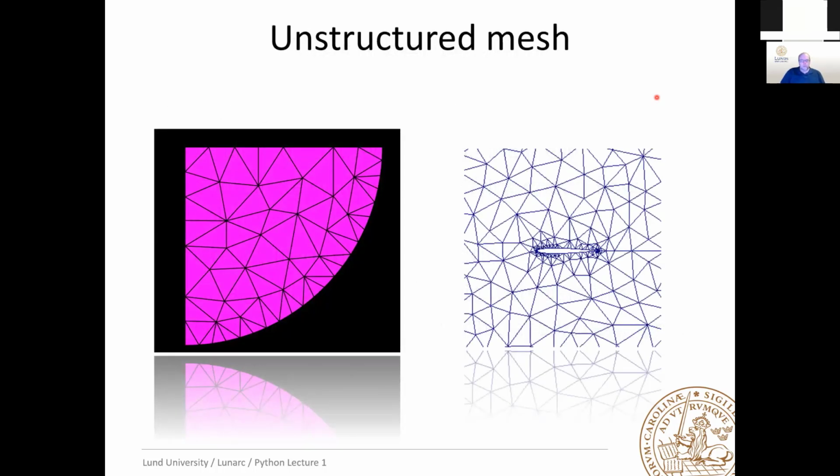This is an example of an unstructured mesh. Here you can see that you have a geometry, and then you have basically poured the elements inside the geometric boundary. The algorithm will fill the mesh with points and then connect them together to form a mesh. And usually these mesh algorithms start from the boundaries and move in. You can see the kind of wavefront here on the mesh, that it moves in so that it completely fills up the geometry.